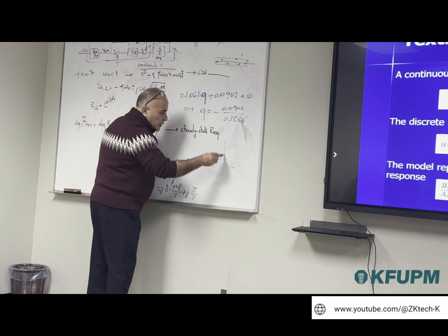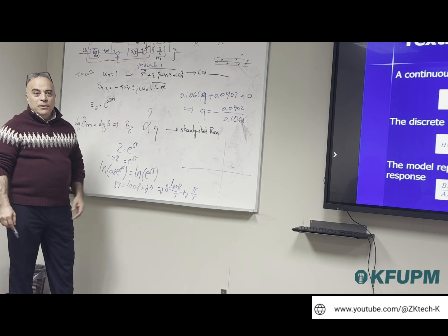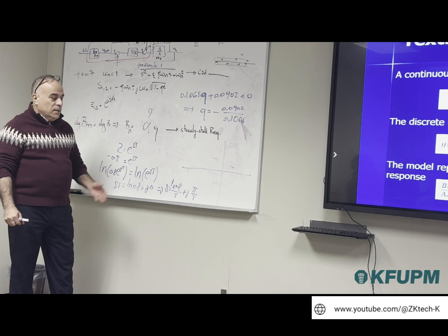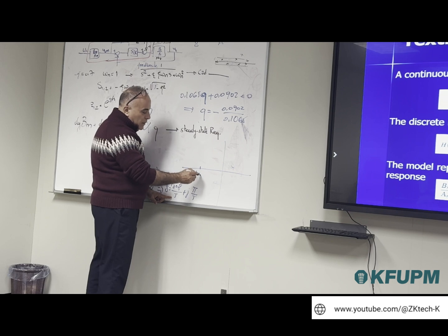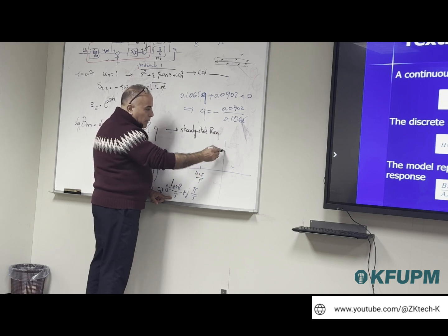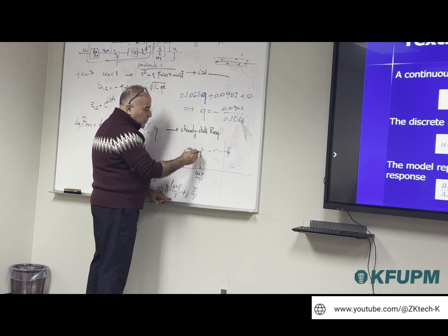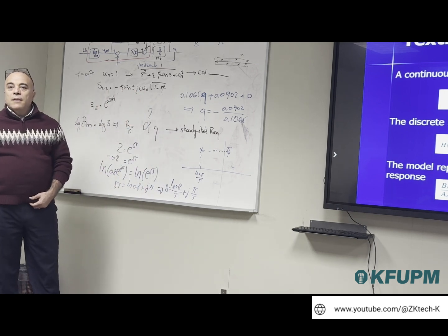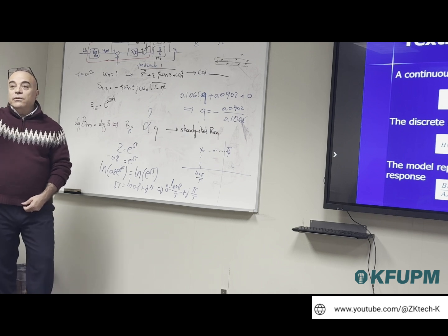So basically, if you look at it in the complex plane now, you will do this maybe one time, and after that you will be okay. But at least you know from where it's coming. When you do this in the complex plane, what you will see is that we have the real part equal to ln of 0.8 divided by capital T. The imaginary part is pi over capital T. And then the pole is here. The zero is here. Which means stable imaginary. What does it mean, stable imaginary? It has oscillations. It will create oscillations.